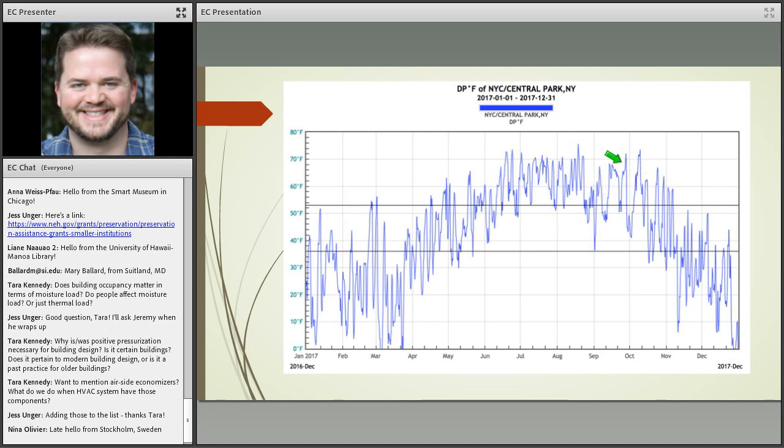That is a note, I think, for next time that I'll try to keep in mind, is to certainly do both. But for everything that is over 53 degrees Fahrenheit, we do still have to dehumidify. And that has reduced, if you will, the overall amount of moisture control that we need to do. In other words, there are a few more days right here underneath the line between 50 and 53 where we've said that the outdoor moisture content is okay.